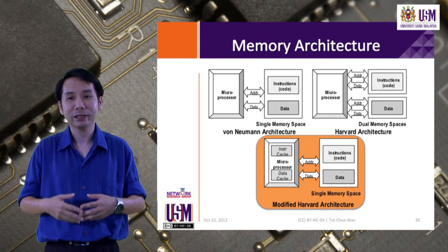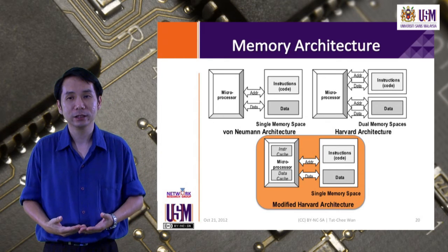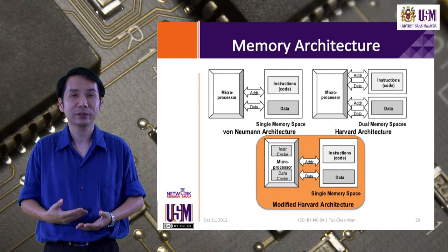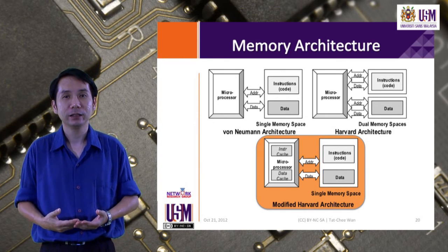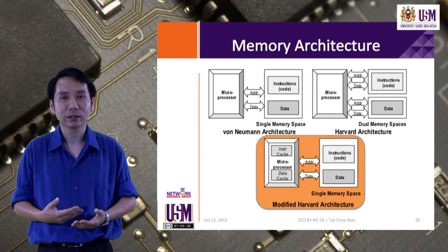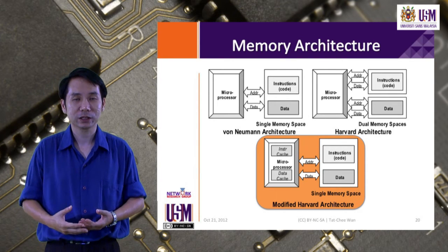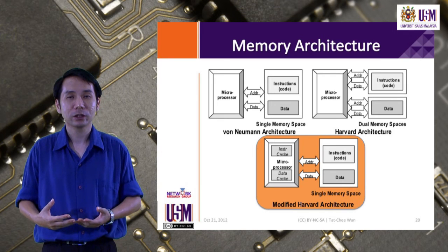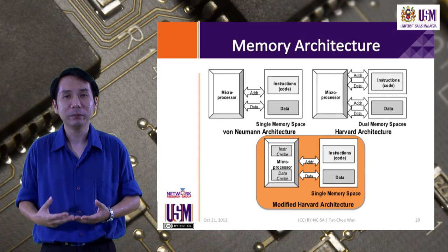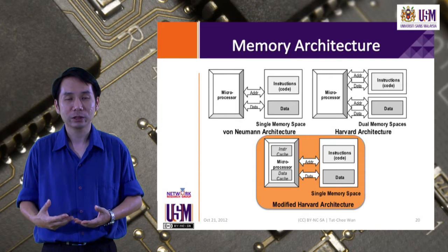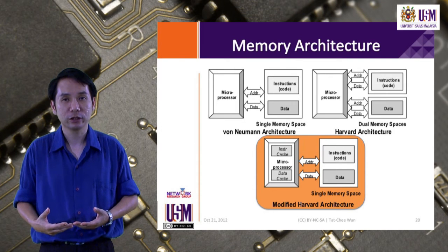On the other hand, the Harvard hardware architecture is much more complicated. It requires two separate sets of data and address buses, and if you have all these components outside of the processor package, this will cause the device to contain many traces to support this dual bus architecture.